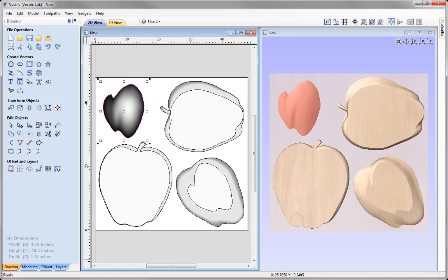Now, one of the things that could be beneficial is to set up a toolpath just to mark the top of the material on the flat areas and then drill holes through it in order to hold these parts down. However, this isn't going to help you with this top piece here because you don't want to damage the top piece by drilling through it. Another thing that will provide you with some challenges when cutting a part like this out are the very thin areas such as the stalk and the top piece of the apple here. And so how you hold these parts in place and how you're going to get enough material as you start to rough, finish and cut the part needs a little bit of thinking.